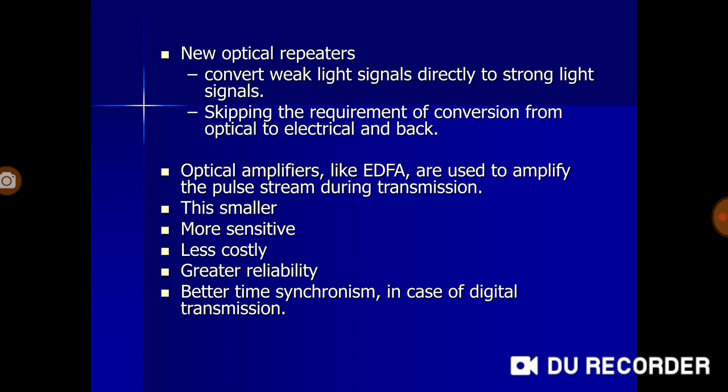Present day, we have optical amplifiers like erbium doped fiber amplifiers. The fibers are doped with certain materials, erbium. So it happens that when light is traveling across the fiber, which itself is a waveguide, an optical waveguide, it hits from wall to wall, and since the dopant used is erbium, every time it is striking from one end to the other end, it is being amplified also.